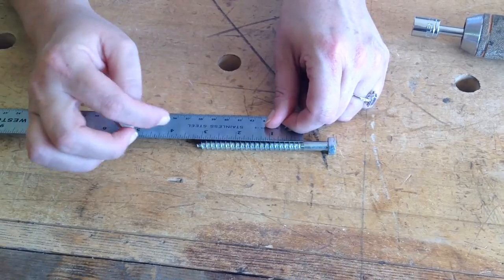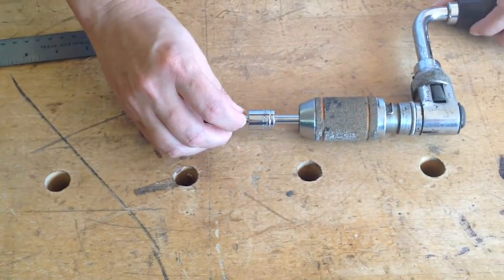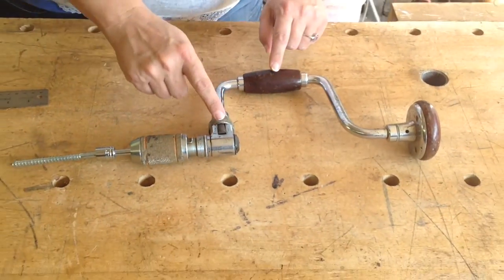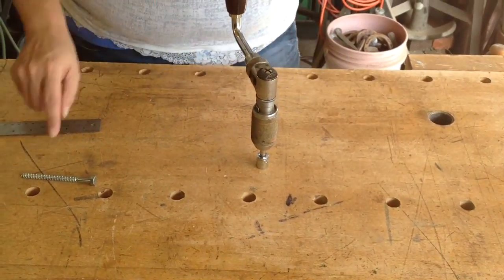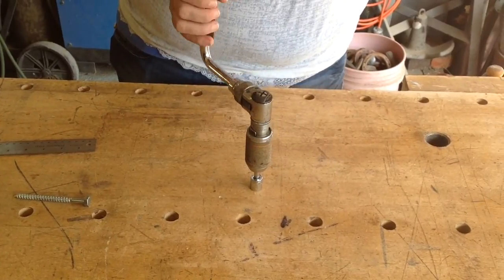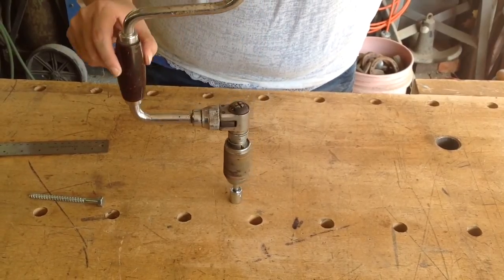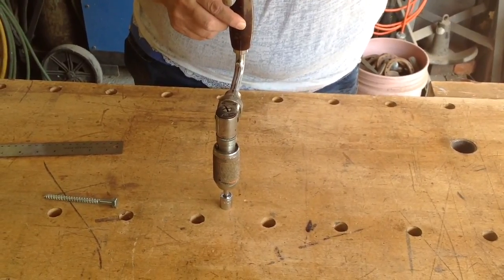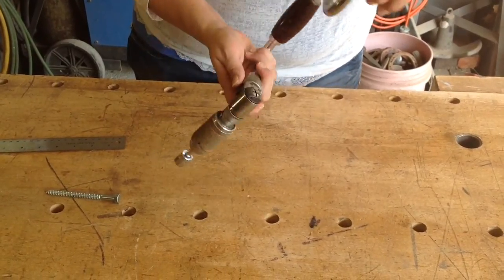Alright, so whenever we hook this to a tool, let's use this one here. I tried to find one with a really good mechanical advantage. We need to find the circumference because whenever I am putting a screw into, say, wood or whatever medium I'm putting it into, one full rotation, my effort, is going to be the circumference of this circle. So to find circumference, it is just going to be 2 times the radius times pi. So we need to find that radius.